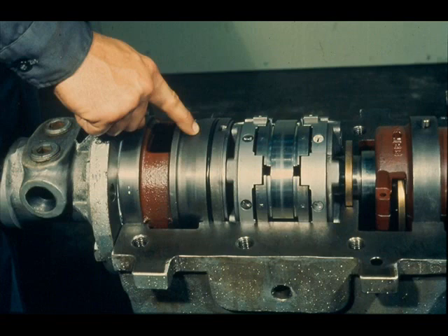Now, by removing the pump bracket and lifting out the thrust bearings, we are able to see the shaft adjustment shim pack. By shortening or lengthening the shim here, we are able to adjust the lateral position of the shaft to ensure that the rotating element of the machine is properly positioned in its case within limits of the adjustment.